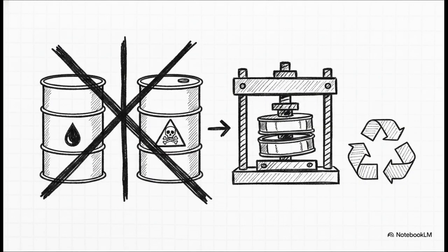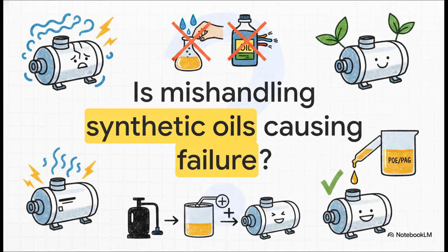When it comes to compliance, the rules are really grounded in just basic, strict housekeeping. All containers have to be clearly labeled as used oil. And guys, never ever mix used oil with solvents or hazardous waste. Doing that triggers a massive, incredibly costly hazardous waste nightmare. As for oil filters, you've got to puncture them, hot drain them, and completely crush them before you can recycle them as scrap metal.